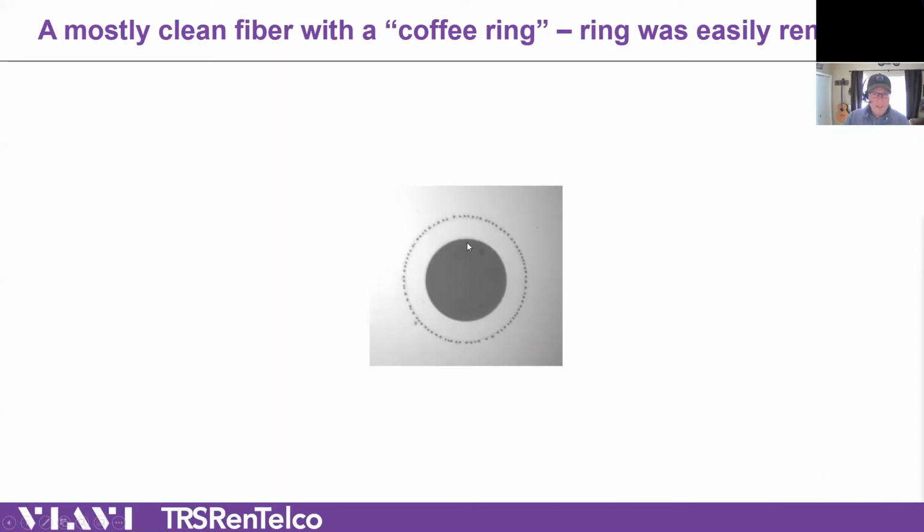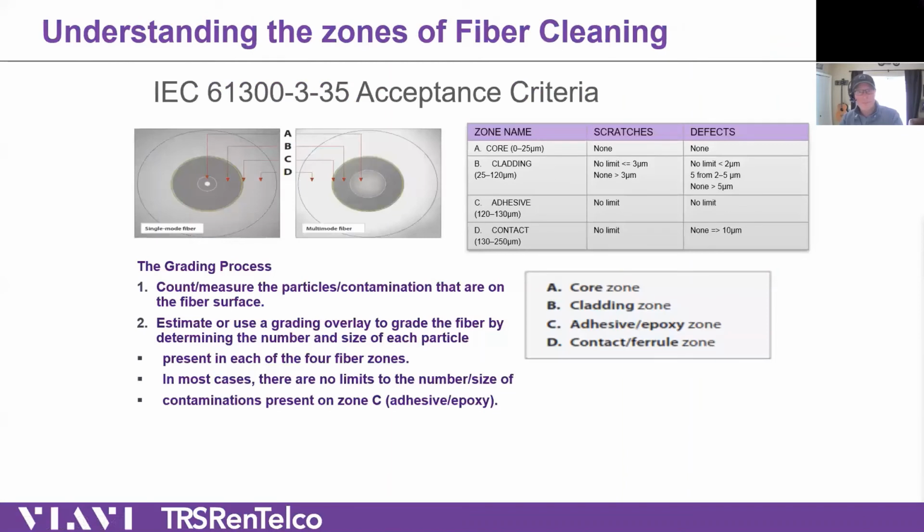The important part of this slide isn't so much the ring on the outside, it's the spots that have burned themselves in on the inside. If there are enough impurities in there, they work like dirt and they create gaps, they create reflections, they're non-cleanable. But the tell sign is that ring around the side, right? For those who've played with fiber, you've seen it most likely. If not, just rub your thumb across it and go look at it with a microscope. And then you can amaze your friends at parties with how gross your skin really is. And not anyone in particular, just in general.